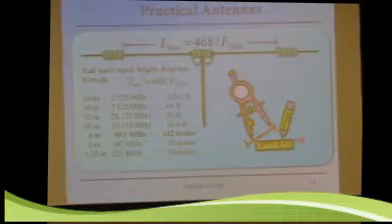If you look at 2 meters, it says 38. Remember, that's a half-wave dipole. What I was looking at was a quarter wave width. And that's at 147 megahertz, and I think I was down at 146, or anyway. But it does work even for 2 meters. You just have to convert the feet to inches.